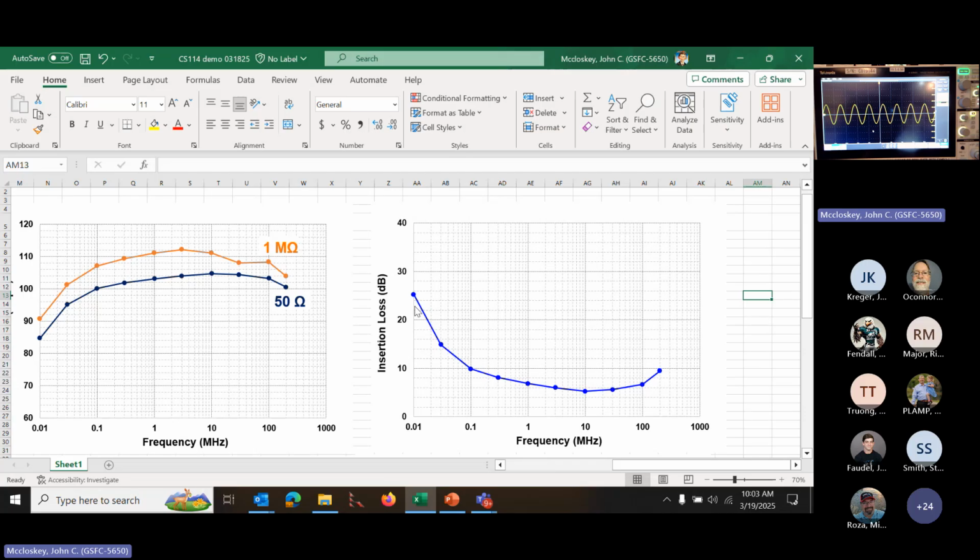Now this is a very crude measurement with just at each decade, and then at 3 times the decade level, right? So 10 kilohertz, 30 kilohertz, and so on. 3 is roughly halfway between. To do this more comprehensively, you use a network analyzer, and I've done that, but I just thought it was informative to go into a scope, among other things, to be able to just select the 1 megohm input.